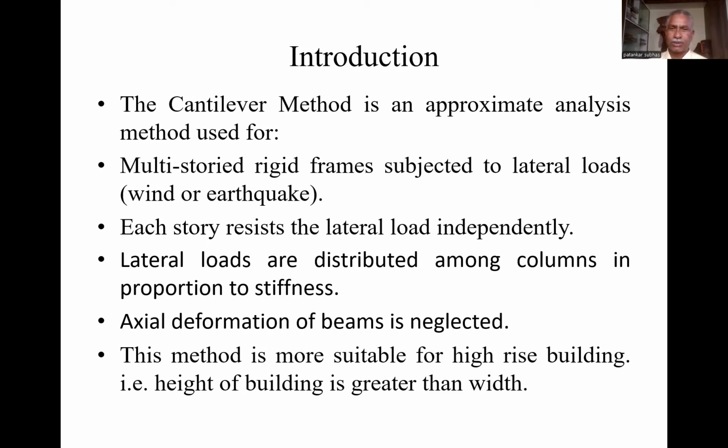When the number of stories is more, then redundancy increases, and that's why it is better to use some approximate methods. There are basically three methods for the horizontal load, that is the wind load or the seismic load, and the method used for the vertical load, that is the live load and the dead load and their combination.